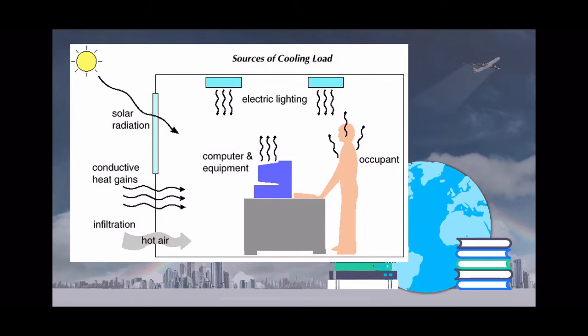So the basic concept is to cool down. To cool down who? To cool down the occupants and to cool down the computer. So technically heat is going to move from a hot place to a cold place. That is thermodynamics rule number 1, right? Heat mainly comes from the solar radiation, and this heat will seep into the walls of the building, as well as other components inside the room which also emit radiation, and finally the bodies of the occupants themselves also emit radiation.